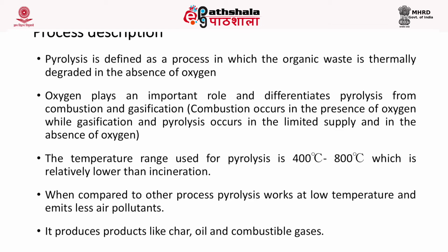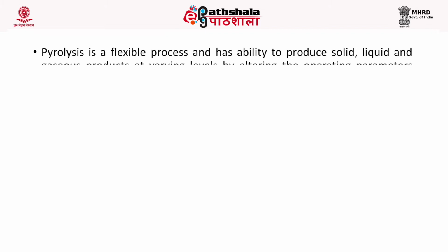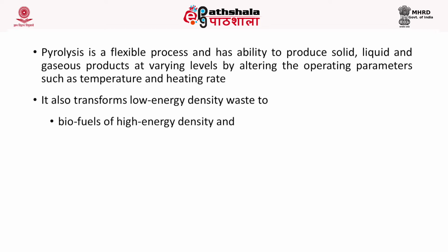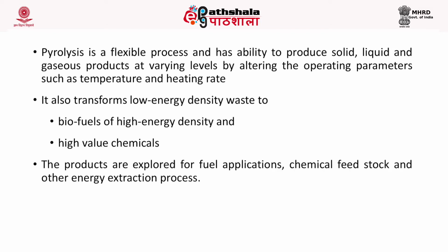When compared to other processes, pyrolysis works at low temperature and thereby emits very few air pollutants, unlike incineration. It produces products like char, which is a solid product, oil, which is liquid, and combustible gases. It's a flexible process and it has the ability to produce these three products, solid, liquid and gaseous, at varying levels by altering the operating parameters such as temperature and heating rate. It also transforms low energy density waste into a biofuel of high energy density and high value chemicals.